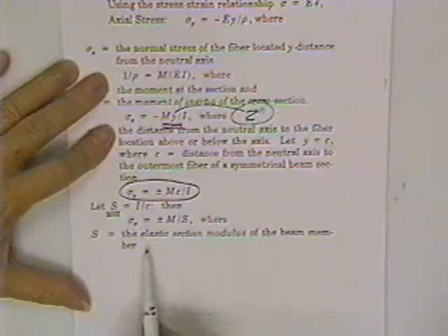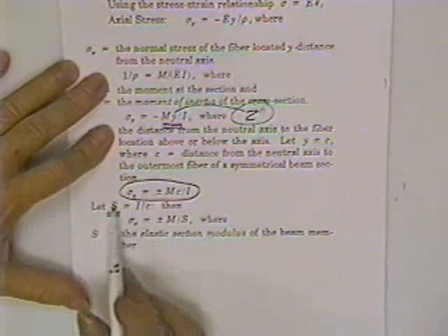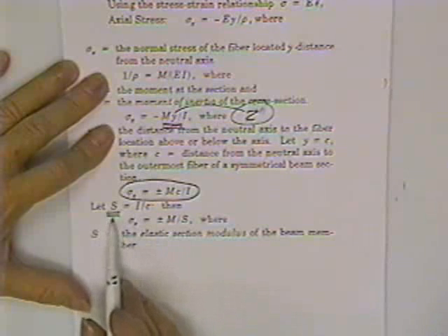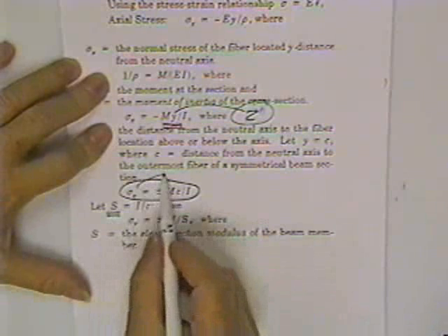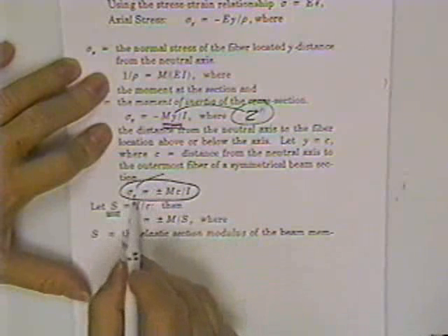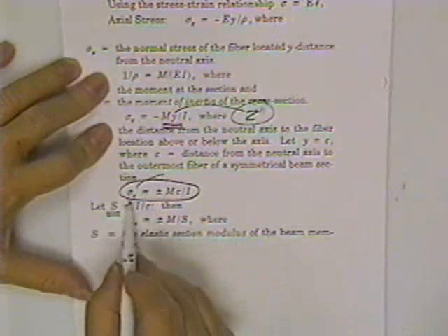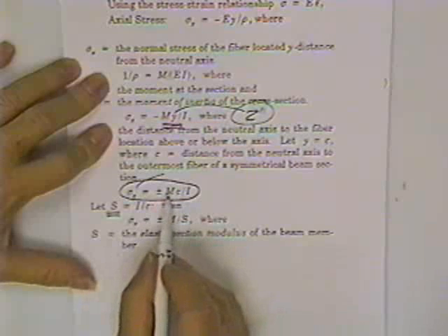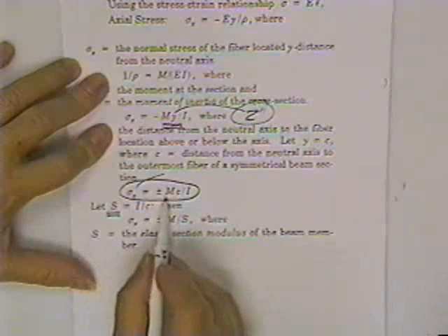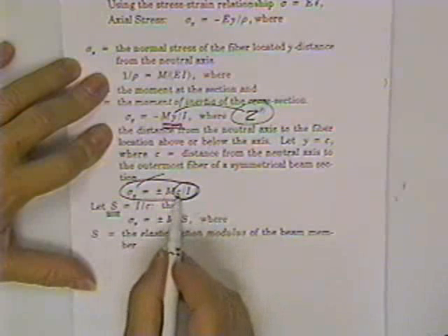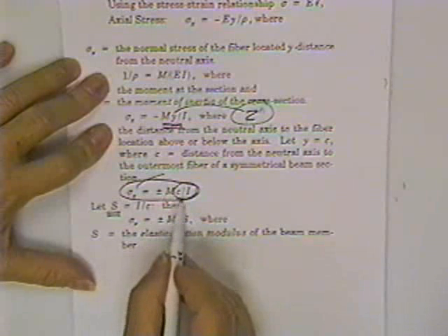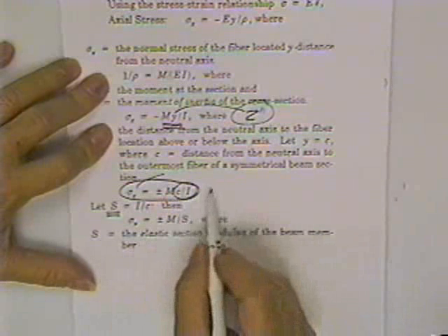He could give you some beam tables, but I think it's a little unlikely. But still, he might ask you something else about a section modulus, so you should know what it is. Where that came from is people were putting the known allowed stress here in the stress slot, and they were putting the moment that they knew had to be carried here, but since they didn't have the beam yet, they didn't know the distance from the neutral axis to the outer fiber on the wide flange, and they also didn't know its moment of inertia.